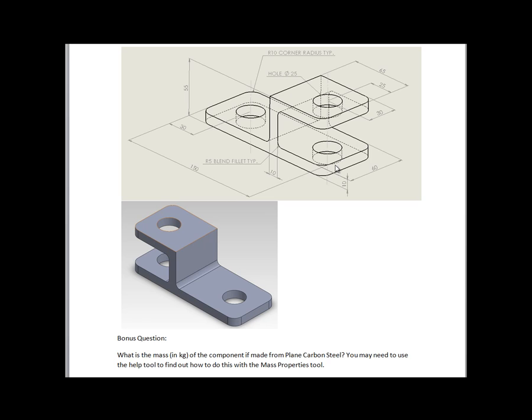We've got a 60mm wide component and the holes are sitting on the midline 30mm from one side, so there's a symmetry running straight through it that way. Also, if we look at it from the side, there is a single profile which is then modified with the holes and the fillets on the corners. So I'm going to approach it by first drawing this profile shape that we can then extrude, incorporating the symmetry line.